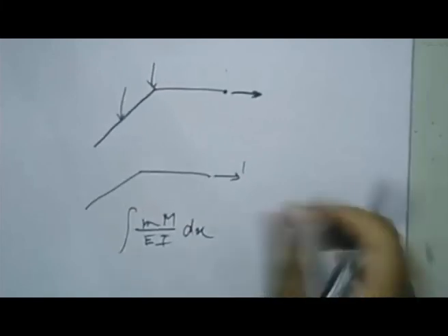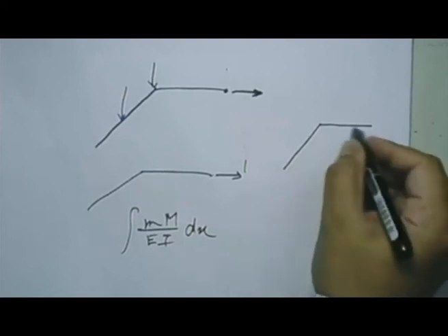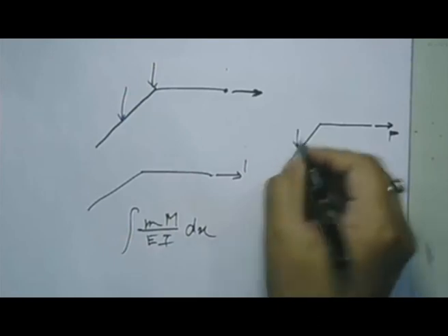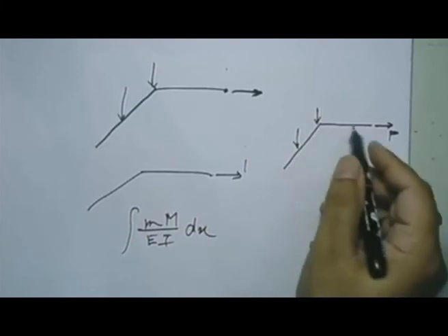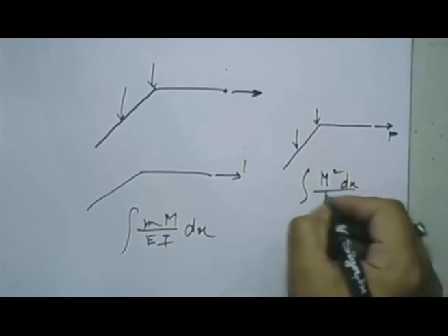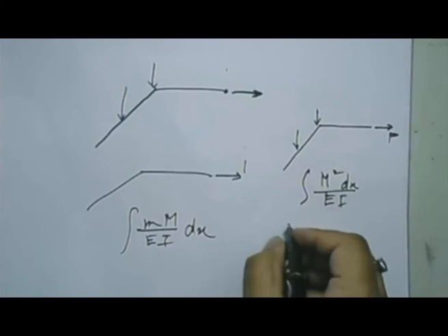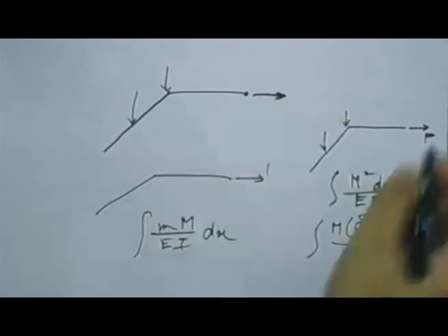Now, the only difference here is when you are trying to solve this by Castigliano's method, instead of applying the actual load here, you apply the load P and you apply the other external loads. You calculate the strain energy due to bending in this member and this member. That will be given by formula M square dx over 2EI. Now here M will be a function of P. So then you take the partial derivative with respect to P. Now again here P would be not equal to 0 but equal to 60. That is the value of the actual load that has been applied here.